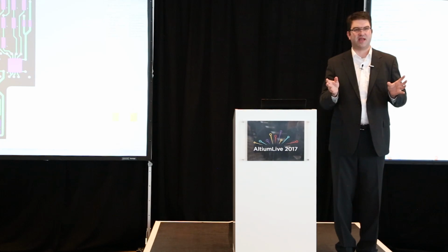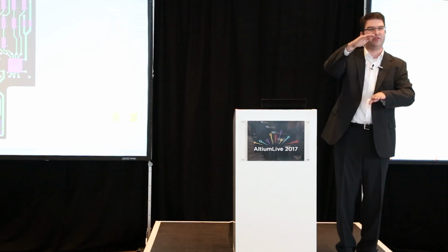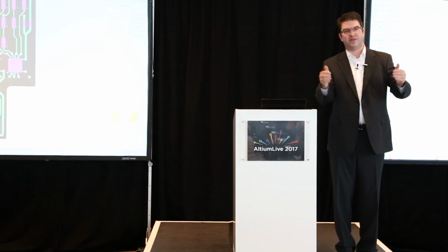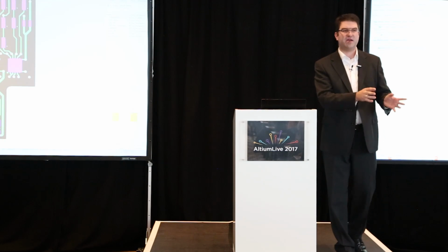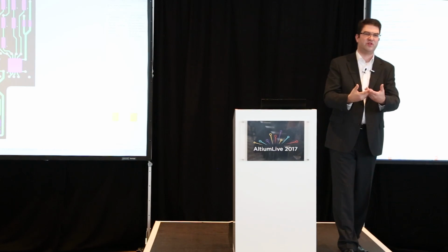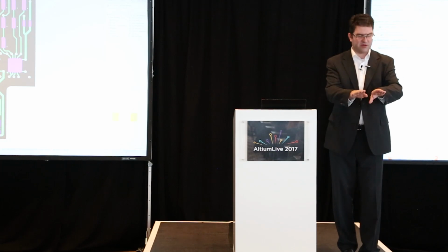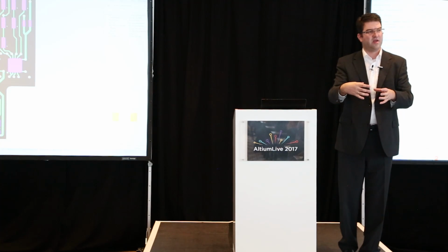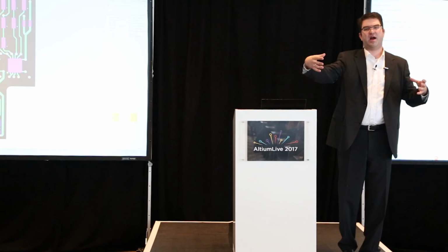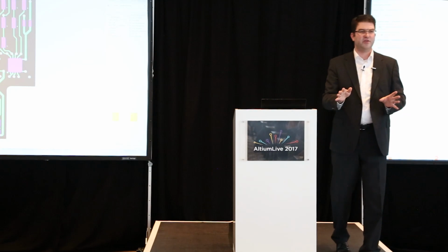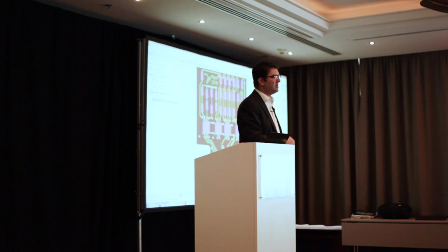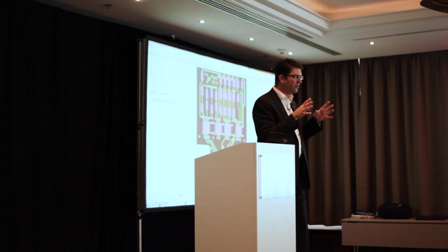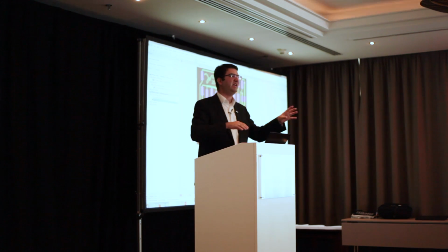So it's basically a three-dimensional calculation, how much free resin you will get from the prepregs you're using, and from the volume you have in your components and the cutout. So you can calculate on one hand, is there still enough resin to fill everything? That's one part. The second part is we know exactly how far these resins will still flow. So they need to go underneath components, on top of components. They need to fill spaces. And you cannot populate the whole area and have the resin flow 2 centimeters. That wouldn't work. So there are restrictions behind that we know. And actually, this is something on the last slides, that there is a restriction in the grouping of the components so that the resin can flow on each area so that everything is being covered and void-free.